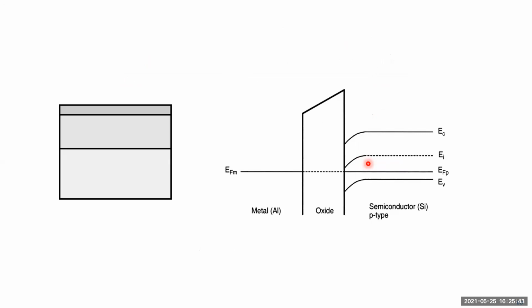Okay, now I'm going to quickly show you the same sequence but with the band diagram. When you join this metal and oxide, taking this sandwich, if you take the band diagram of it, you can see that because the Fermi level needs to be the same for this entire conglomerate, and the work functions are different, the bands will bend in a certain direction depending on the type of material. Here, if it is a p-type with a metal and an oxide, the band bends in the direction where the channel will get inverted. In fact, it does get inverted.